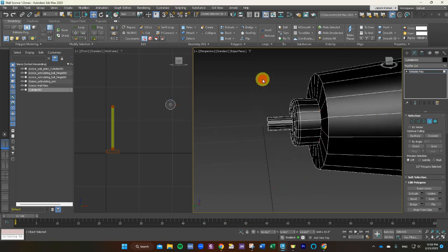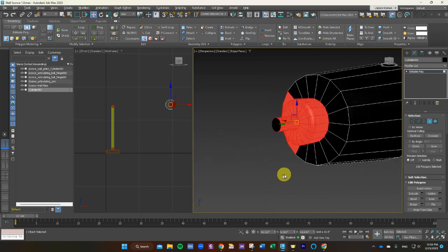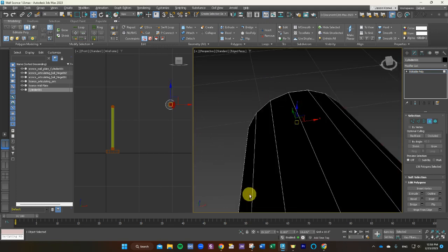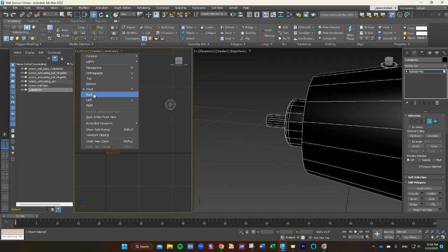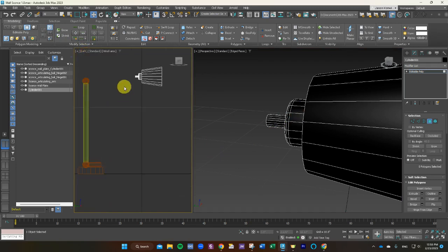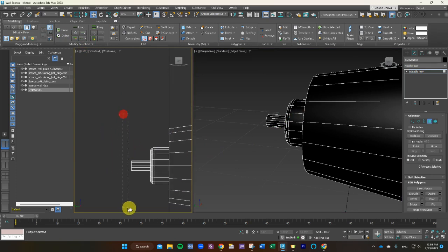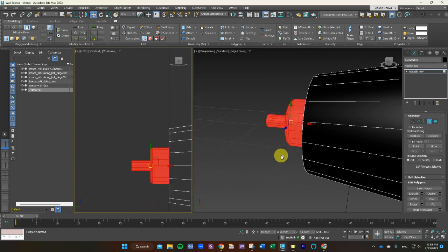Now, if I'm a little bit crooked and I do that, watch what happens, okay? I go like this, I think, oh, right there, perfect. And I swing it around. What happened is it still caught some of those in there, right? Because of my angle. So a lot of times what I would rather do is switch views and go to a right view, a left view, and then you have a perfectly straight line, real quick and easy to draw a window, and that's what we do.